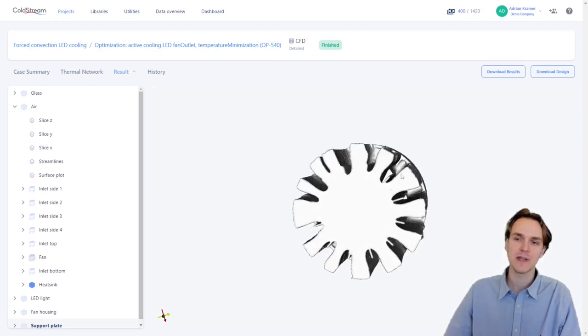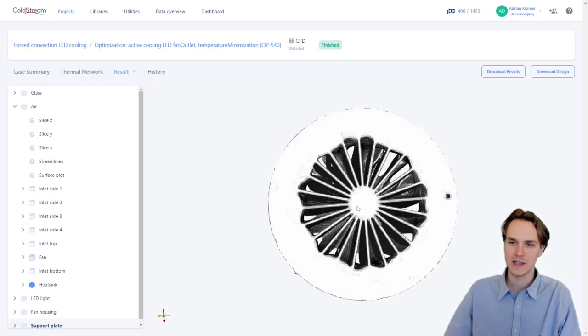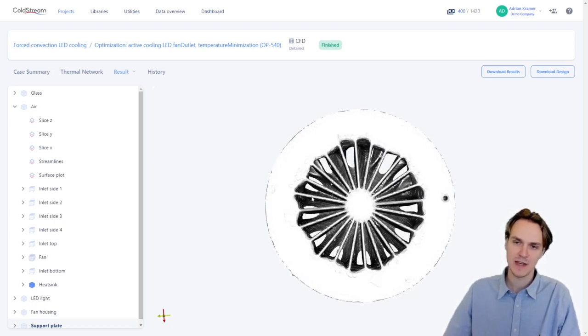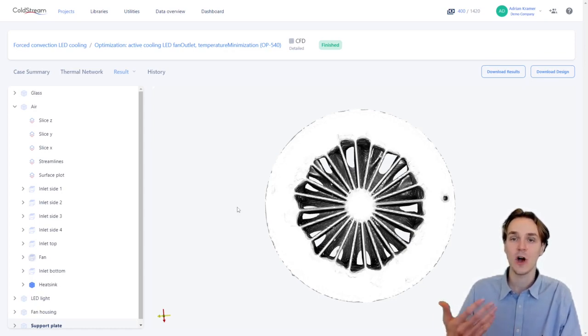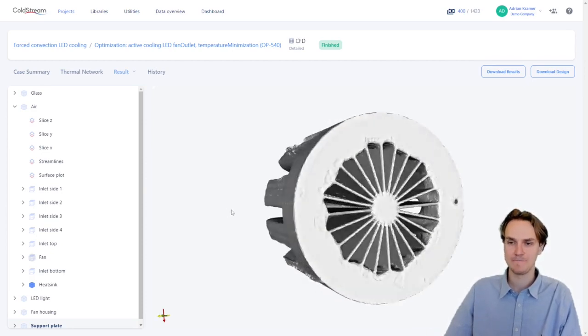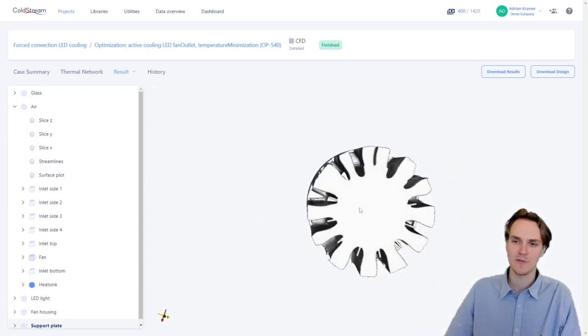The reason being is simply, you can see quite nicely here that this design creates these thin slits, and actually you create a higher effective contact area between air and solid, which of course aids with the heat transfer. In addition, because these air passageways are so narrow, it actually made the air velocity of the airflow higher, which also helps with the performance of the heat transfer. So those two things in combination made for a better performing heatsink.